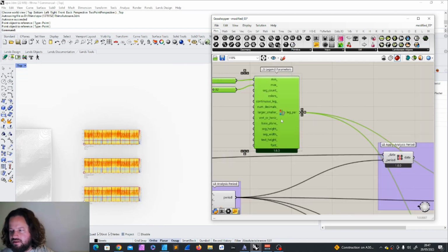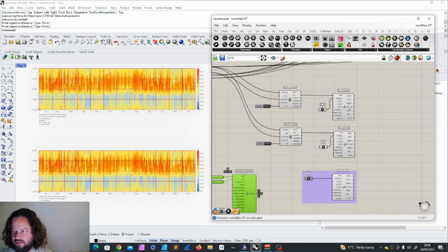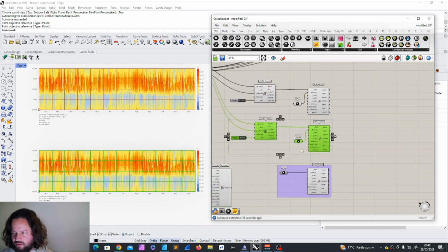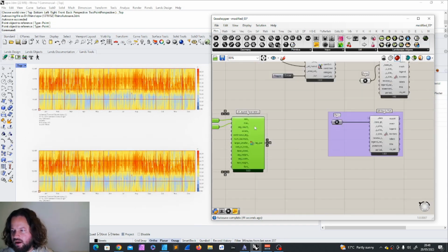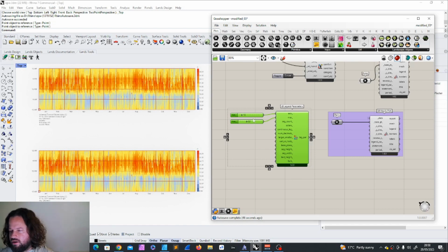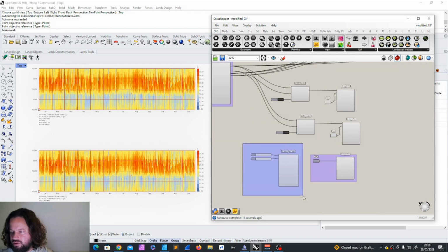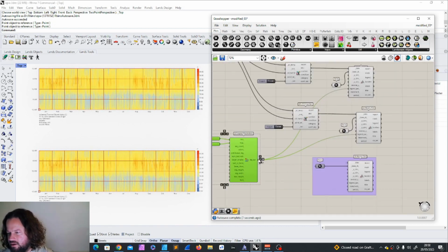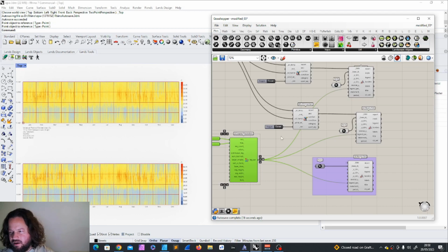So I take this and make a copy. Now we have the UTCI, where we just take the minimum required input. Then in the second one, we will add the mean radiant temperature and also the wind velocity and see how that changes. Now legend parameters. Let's keep it more open, so we add a bit more and create a larger range. And we can then use legend parameters here, and here. And now we see quite a difference.